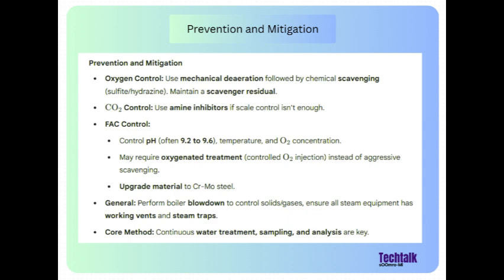Clever. Also, basic maintenance is vital. Making sure vents that release non-condensable gases are working, and ensuring steam traps are doing their job. Steam traps, they drain away the condensed water, right? Exactly. If they fail, water backs up, CO2 gets concentrated, and the acid attack gets much worse.